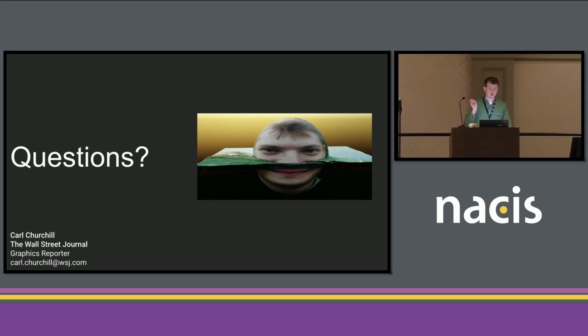In terms of imagery, for the US, USGS NAIP is really great ortho imagery to use. Sentinel-2, which you can access through the Copernicus browser for free, is really good to use. I often use Google Earth Engine to make mosaics. And then normally for demos, I'll use a WMS of Google imagery and then replace it with something else later on for licensing reasons, just to give me a sense of where it is. And also, honestly, Natural Earth base maps are really good to use for big regional swaths.